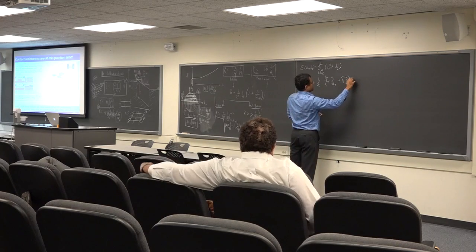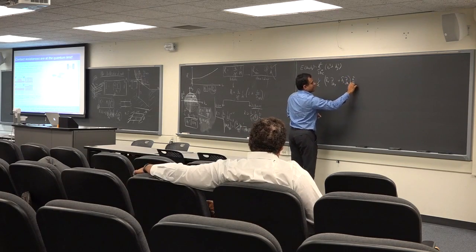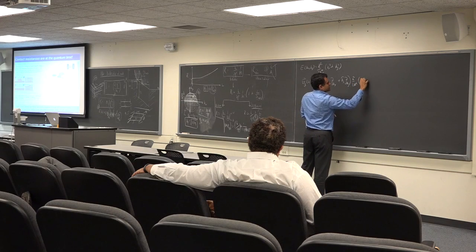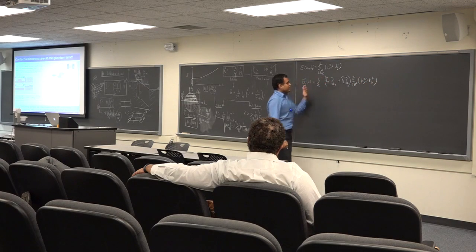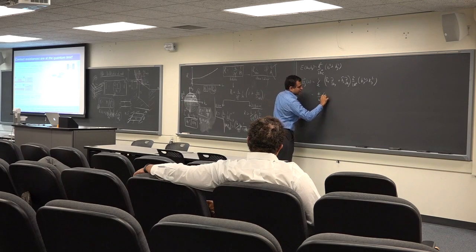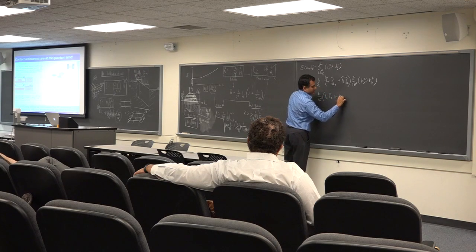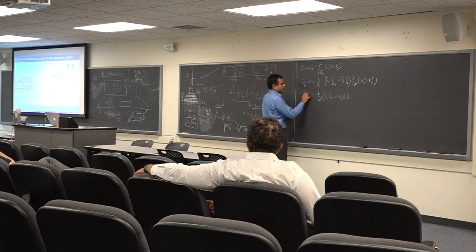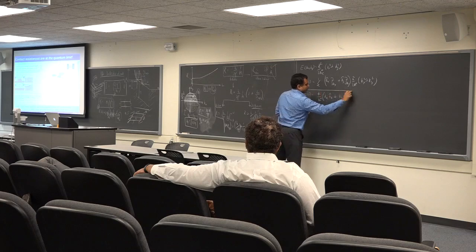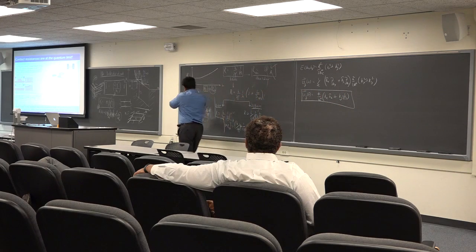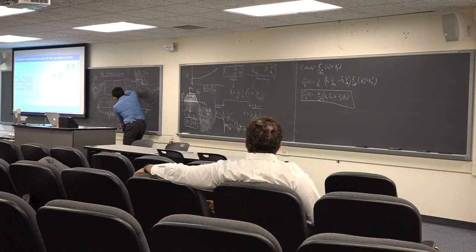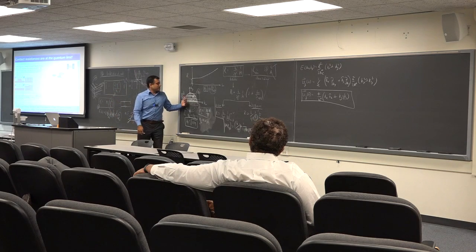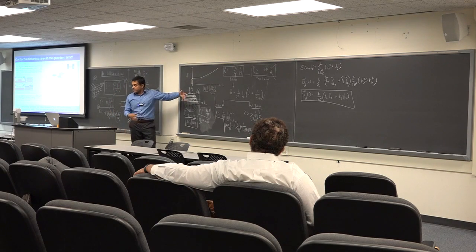That's Cartesian coordinates, on kx squared plus ky squared, right? Once you are done with that, what you get is h bar over m star times kx times the unit vector along x, plus ky times the unit vector along y. So that's your group velocity of any k state. This is a very important parameter which we are going to use to differentiate between a real parallel connection of many 1D conductors, and then calculate the current of a ballistic transistor from here.